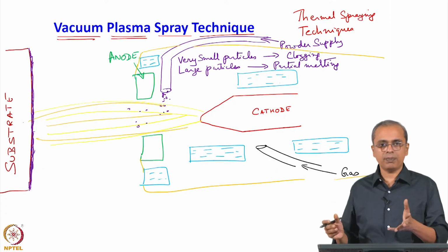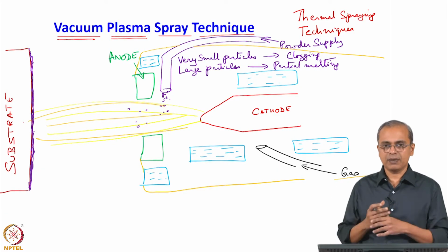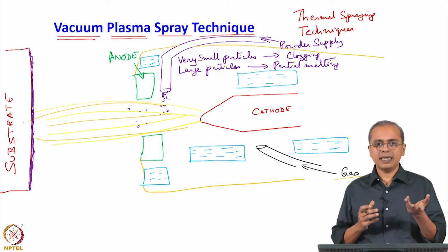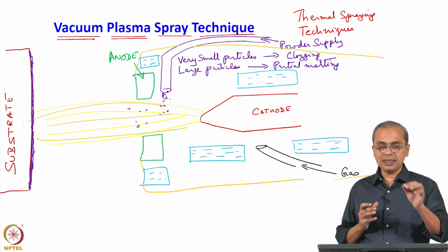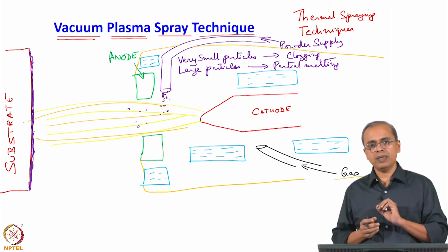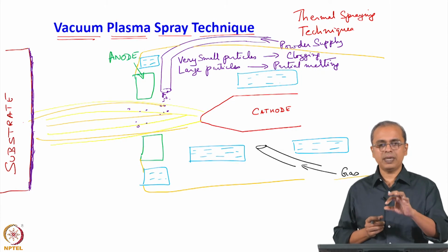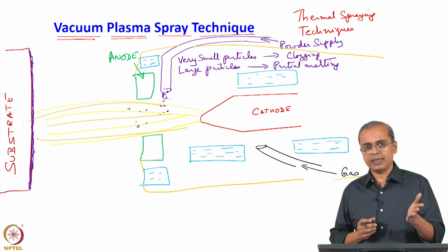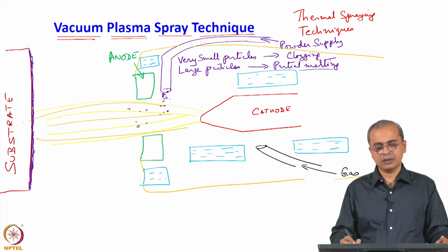If you take an 80 micron particle, let us say they are all crystals, maybe just 1 or 2 grains inside that 80 micron particle, then you are looking at, say, 40 to 80 micron crystal size. If it does not melt, then you will still have a residual, say, 20 micron crystal size, which does not help us. Maybe 20 micron melts and becomes nanostructure because of the sudden cooling, but the other 20 micron has not melted. So, partial melting does not help us.